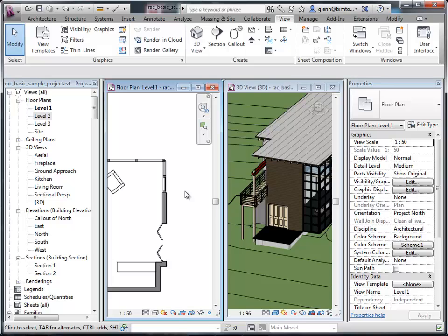We could run a tool on your model after the fact to verify that the doors you have on the exterior wall are actually good exterior doors, or that doors don't swing into each other, that we have good clearances for ADA. There's all those things we can do. The modeling tool itself won't tend to fight you on these things. It'll let you do things that aren't necessarily the most sensible. You can always say, hey, analyze this and tell me if I'm making sensible assumptions.